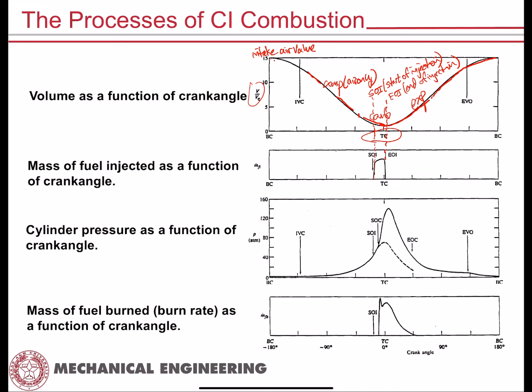Okay, so if we look now at the third plot, the cylinder pressure as a function of crank angle, this one here, you'll see that we have SOI, start of injection, listed on the slide. And then some number of crank angles after start of injection, you have what is called SOC, and of course SOC is start of combustion.